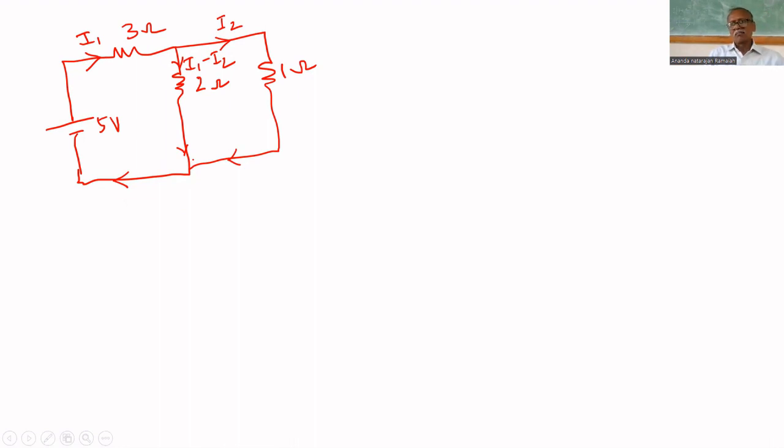This is a simple circuit. But in some complex circuit, you have to check. If 3-4 branches are coming, you have to add and check whether we are getting I1 or not. If you are getting I1, you marked correctly. Yes, we are getting I1. That's why what we marked is correct. It is a simple sum. But finally, you have to check whether you got I1 or not, to check whether we marked correctly or not.